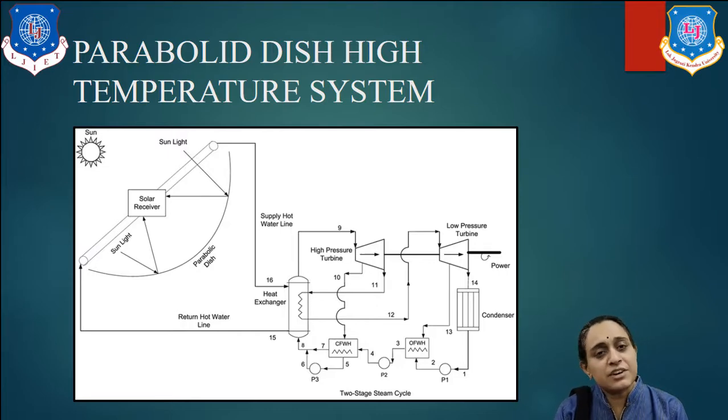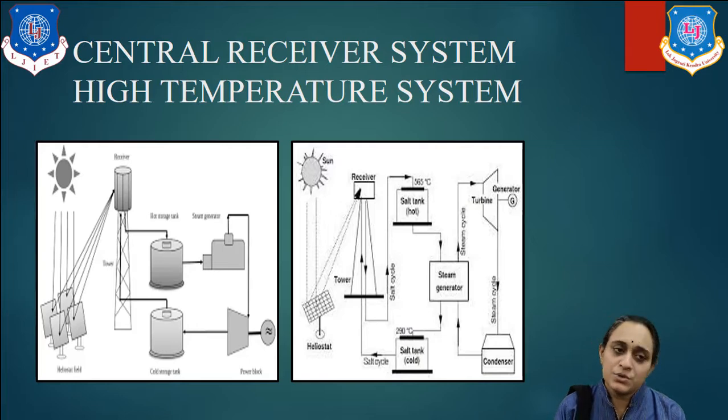Stirling engines are favored, generally known as the prime movers. The system has an efficiency of nearly 0.3 and it develops power of 5 to 50 kilowatt. Such power plants can satisfy the needs of small communities in remote areas, not urban areas. We can use the other ones for those.